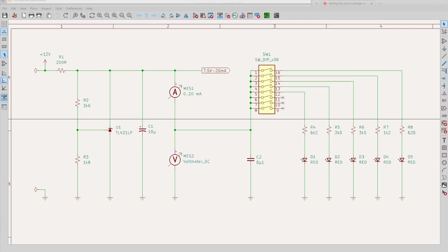On the 200 milliamp range, my milliamp meter uses a 1 ohm shunt, so all I'm seeing is the resistance of the meter, plus about 1/10 of an ohm for the test leads and such. No surprises there. Let me connect the voltmeter to the line side and try again.